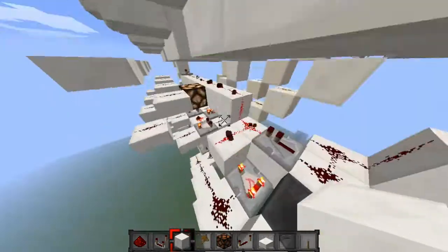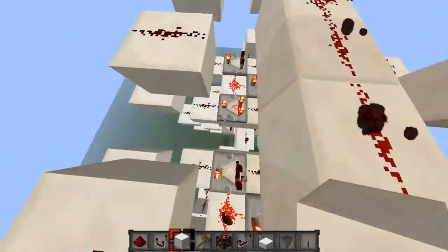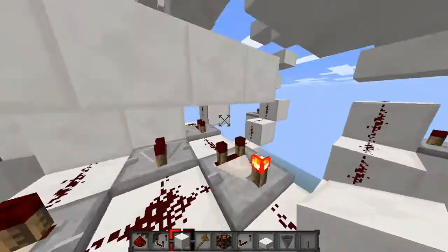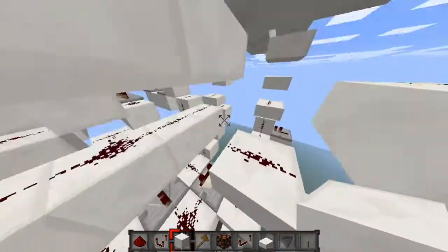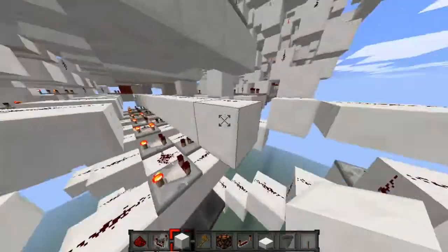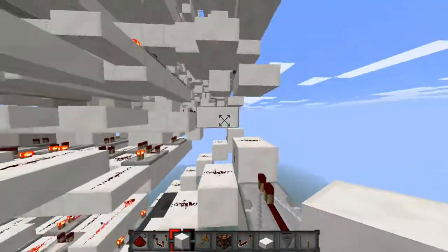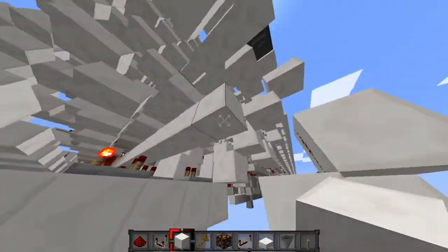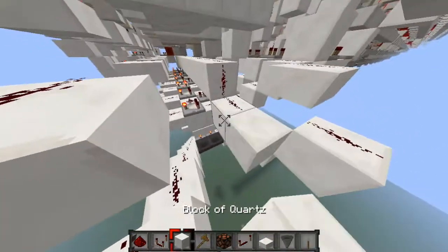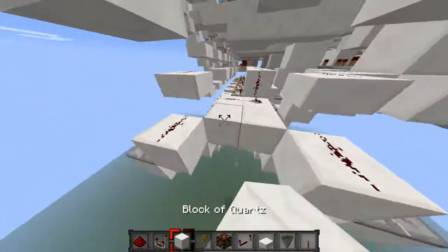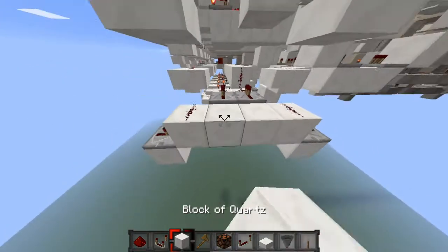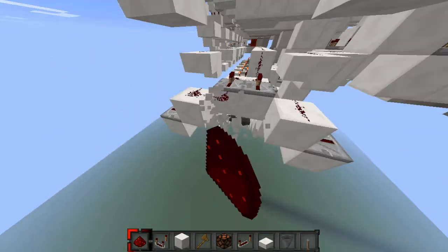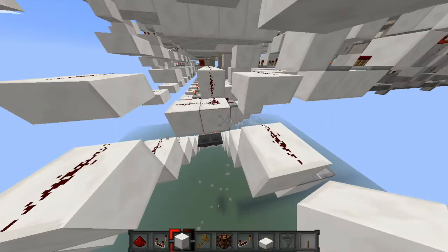But there's still 2 things that we're going to need to finish before we call it quits for today. First of all, we're going to want to connect up the middle input, because this shouldn't be 0 by default all of the time. We want it to be off whenever there's any state that isn't 0, 0 on it. But if we do the exact same process that we've done for all of these so far, and we do something that looks a little bit like this, you might notice that there's a bit of a problem going on right here, and that is that these two have been ORed together, and that is something that we can't do.